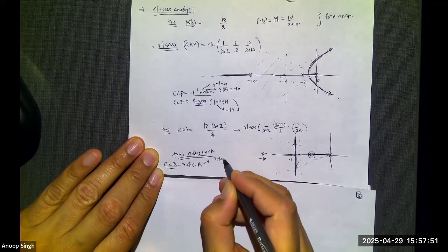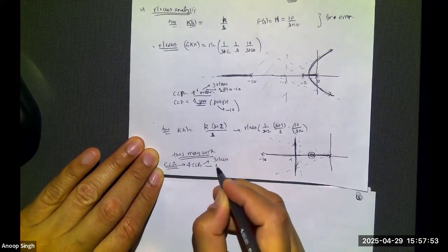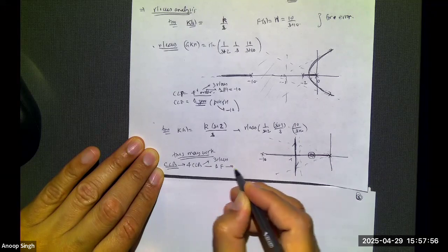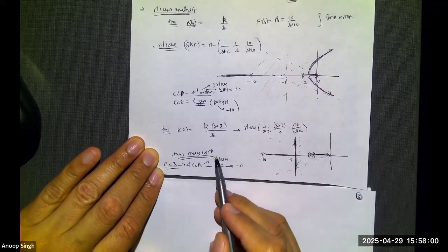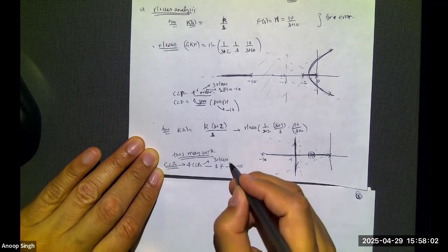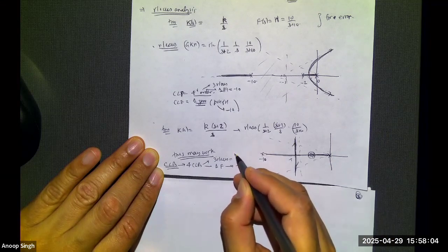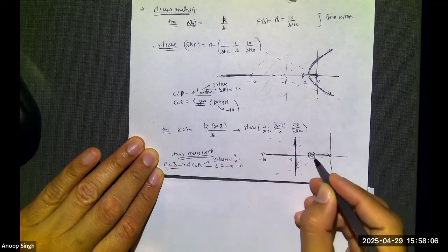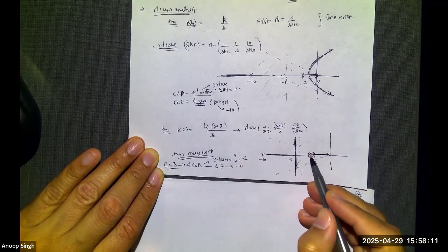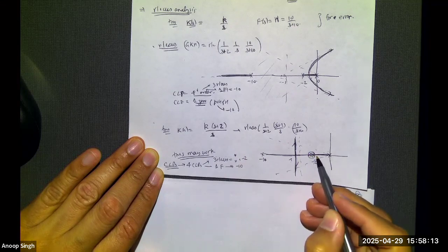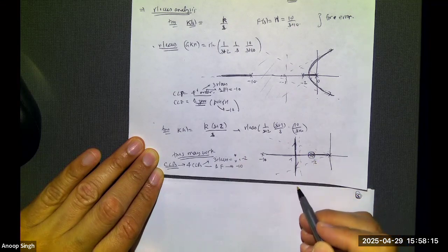three from root locus, one from pre-filter. The one from pre-filter is at -10. Of the three from root locus, two are along these lines, wherever they are. One of them is going to be at -2. This closed loop pole stays around there, starting from here, at -2.